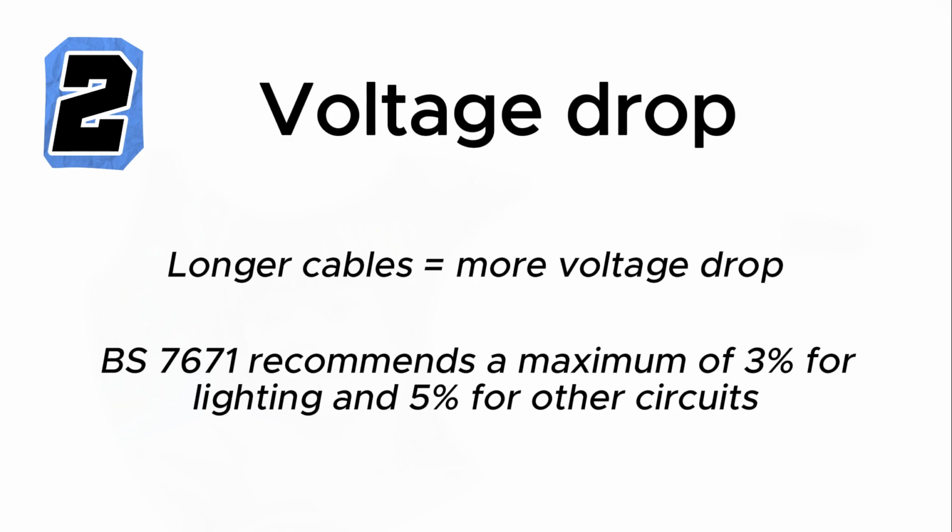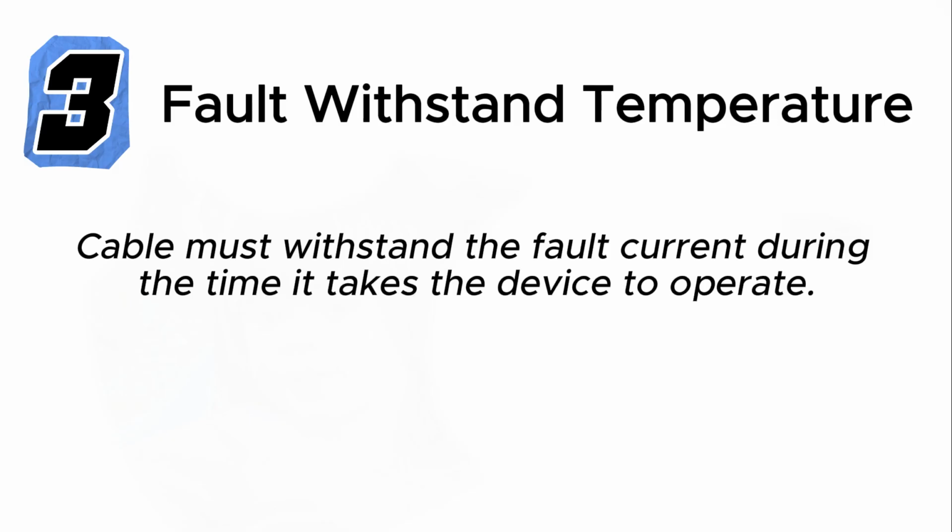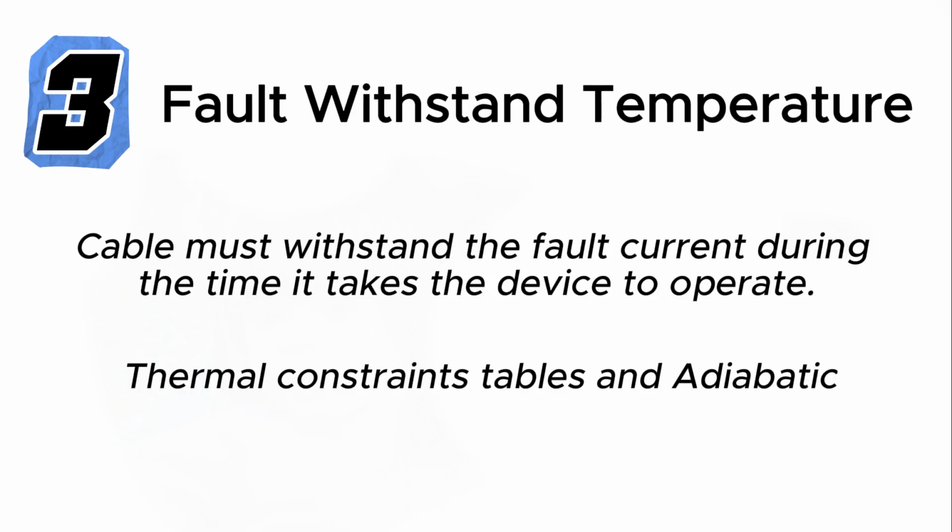BS 7671 recommends a maximum of 3% for lighting and 5% for other circuits. 3. Fault withstand temperature. Your cable must withstand the fault current during the time it takes the device to operate. This is where the thermal constraints tables and adiabatic equation come into play.